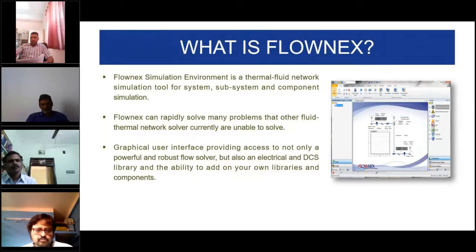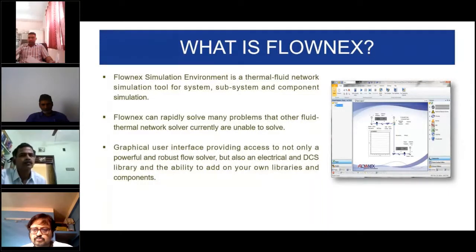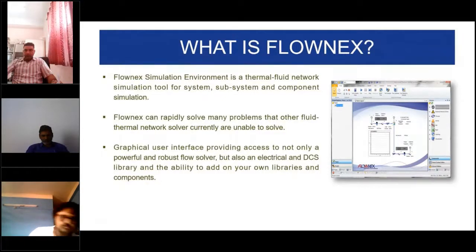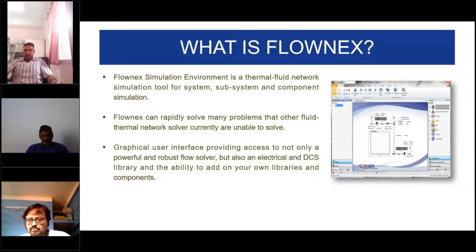Suppose you want to create a digital twin, which is very widely used in industry right now, and people want to control everything through a single screen. For that kind of simulation, you need the digital control system library as well as the electrical library to understand real system behavior. For example, you need to know how your PID is going to lag. If there is a lag, that lag should be reflected in your software also. To create that kind of environment, we need the digital control systems and the electrical systems.